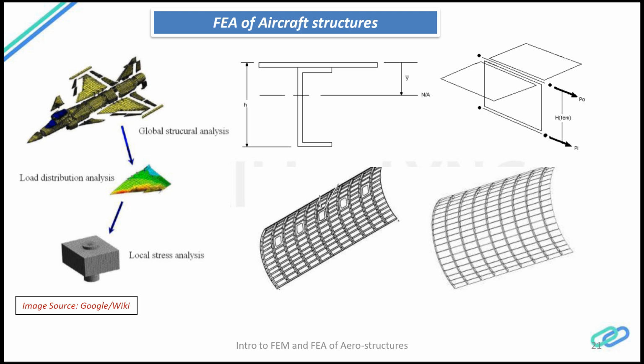using the loads from the global model, you want to run some local analysis on one of its wings, and you have to make the mesh a little bit finer and put in some more detail. You have to model the attachments a little bit and run the wing alone in order to get the stress distribution on the wings.